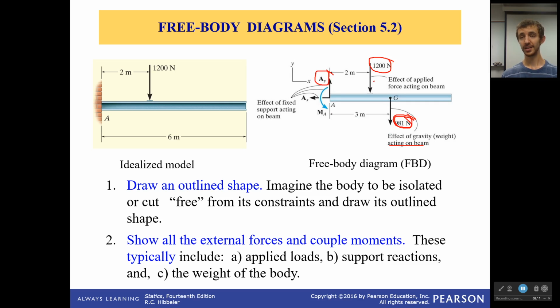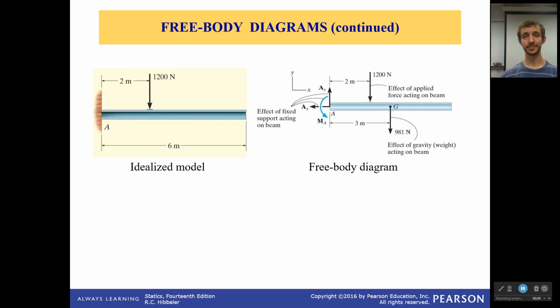Because if I'm looking at the sum of the forces in the Y direction, both of these are pointing down, so they should be added. If I did it wrong, then I would subtract them. I'll get a much different answer. And also, please don't forget the weight of the body. That is one of the biggest mistakes people make, is they forget the weight of the body. Okay.